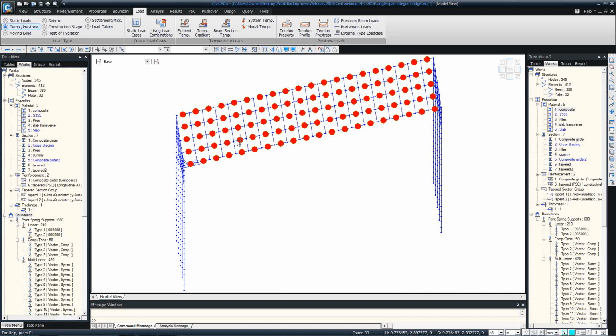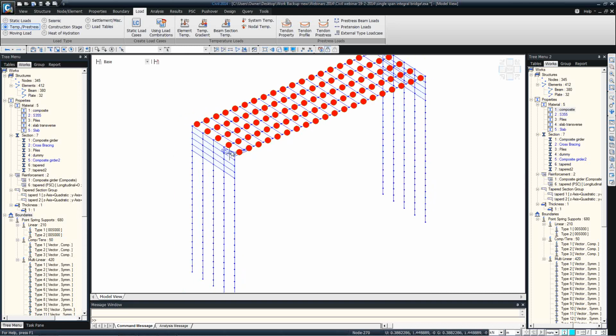Okay, there's one question here regarding the surfacing loads. While applying the surfacing, you should always apply it on the correct part of the carriageway of the deck. Here I just applied it arbitrarily on the girders. If it is a grillage model, then we can go for some dummy beams modeled here, just to represent the extent of the loading.